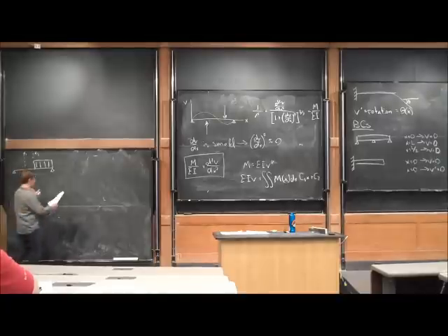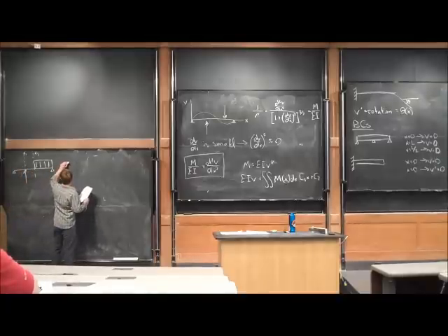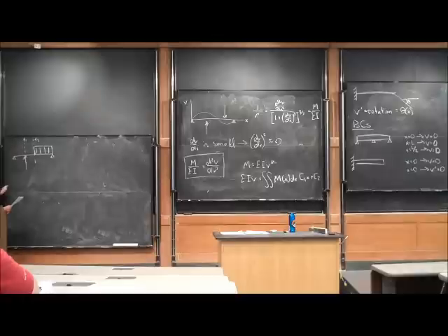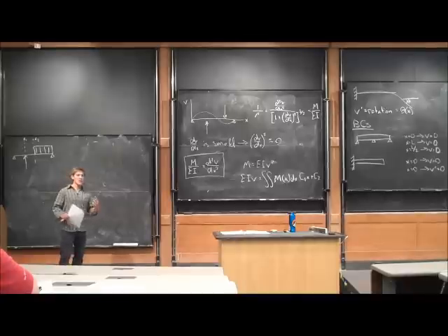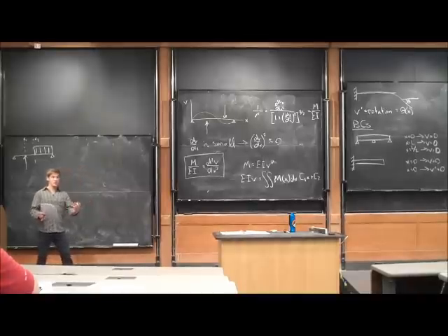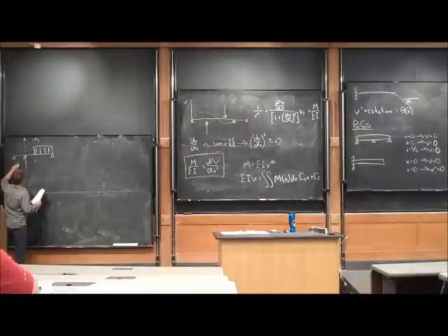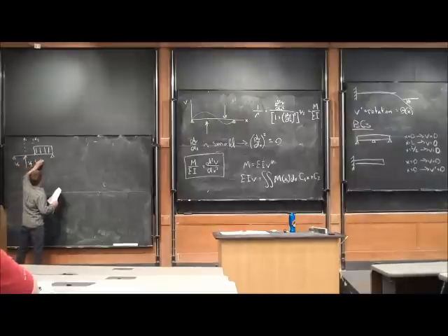We're going to have three equations just like we would for the moment, because if we found the moment as a function of x, we'd have three equations. We can integrate that using that equation right there, and we get three different equations for the deflection of the beam, called V1, V2, and V3.